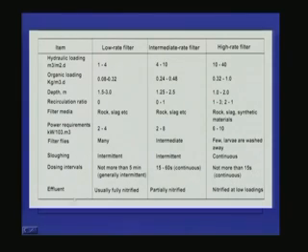And effluent here in standard rate or low rate filter it is usually fully nitrified, that means it does not require any further treatment. And intermediate rate filter it is partially nitrified, and in high rate filter if the organic loading rate is low then we get nitrified liquid. If the loading rate is very high then we will not be getting nitrified effluents.